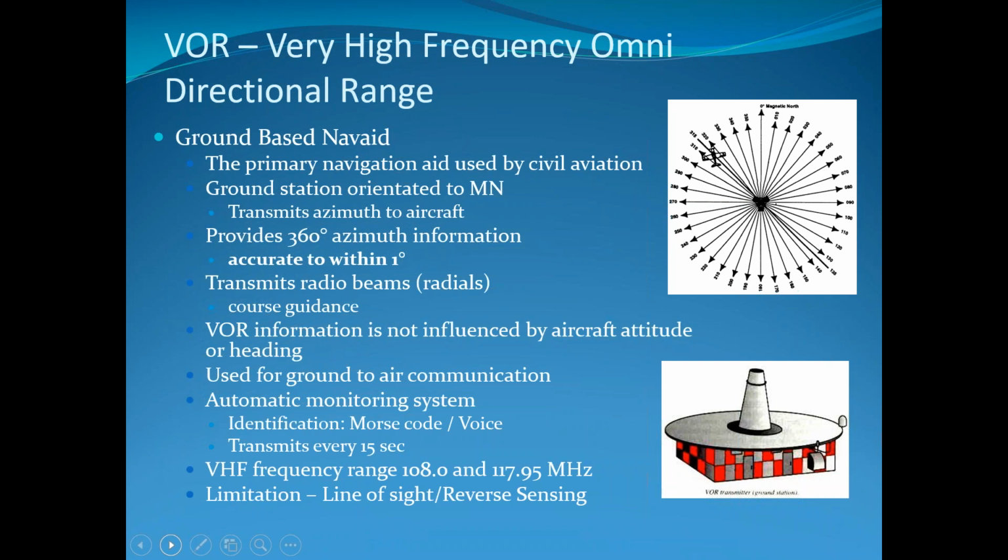If it has a minus 14, all you're doing is taking whatever wind you're reading and subtracting 14 degrees off of the wind. So if it says 190, minus 14 degrees off of 190.